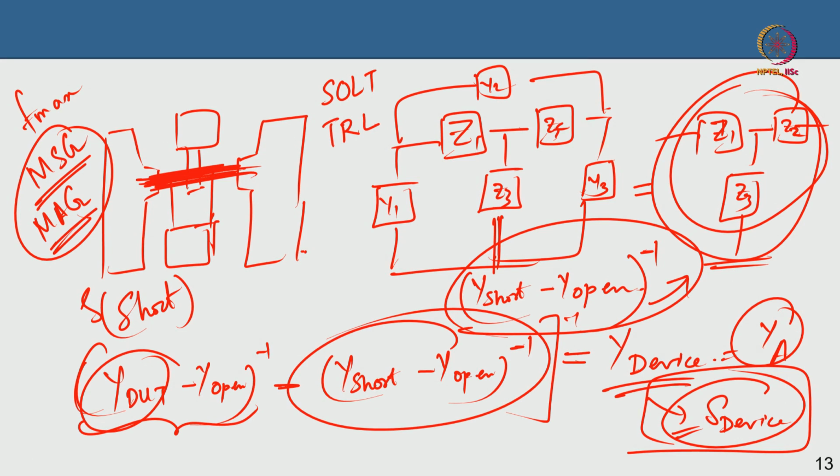However, when you go to CMOS or maybe an RF MOSFET, you do not necessarily have a coplanar ground; the ground will be automatically shorted to the substrate below, so you do not have to have a via hole. The thing in a CMOS-like process is that you put it in a node like a 130 nanometer or 90 nanometer node, and you have a lot of layers of metallic connections, dielectrics, vias, etc.